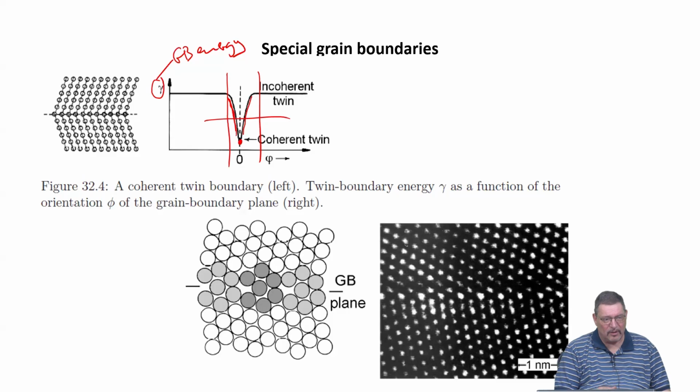And then also it depends on stacking fault energy of the material, because in general, the twin boundary energy is related to a stacking fault energy. And this can be very different for different materials, right? So there can be almost 2 orders of magnitude, 1.5 order of magnitude variation between the stacking fault energies of different materials. And so that all affects how an annealing treatment would serve to get more coherent twin boundaries. But in all materials, the general direction would be if you anneal, you get more coherent boundaries.